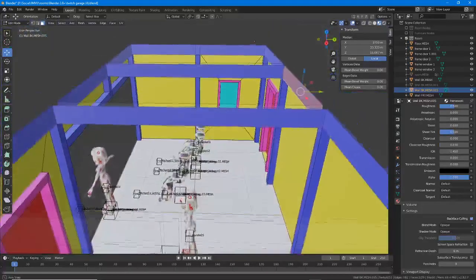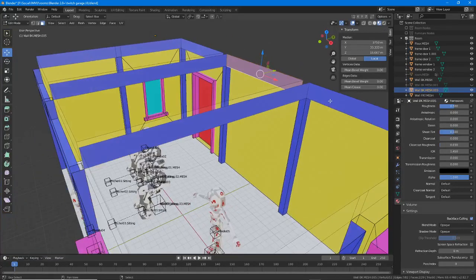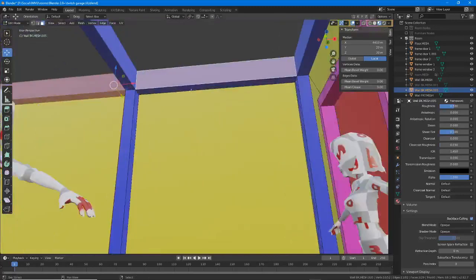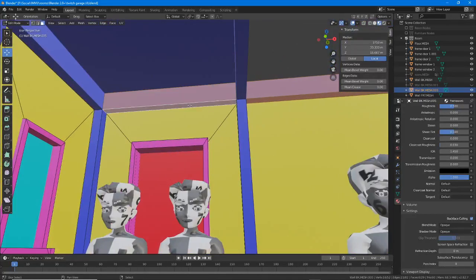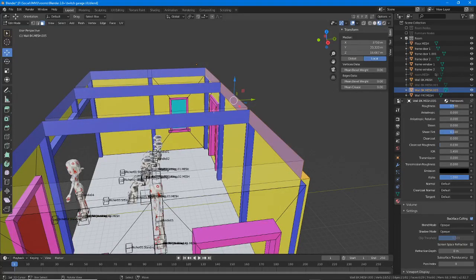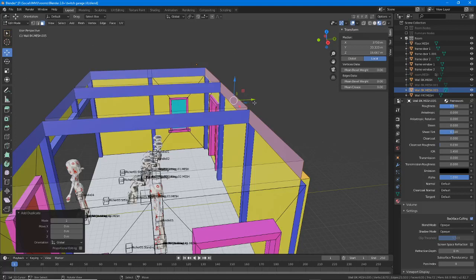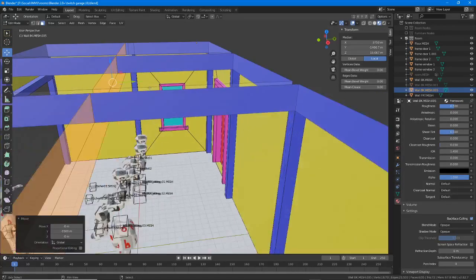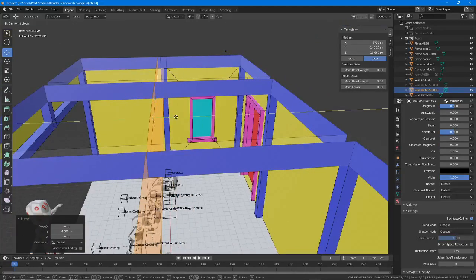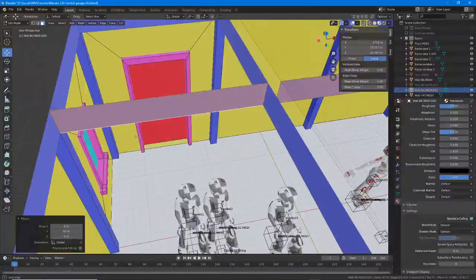So what we can do, just so that we can see the process in action, is use these surfaces, select them, just duplicate, so Shift D or Mesh, duplicate, and again snap to the grid, so we're holding the Control key down, and then Shift Snap for smaller increments.